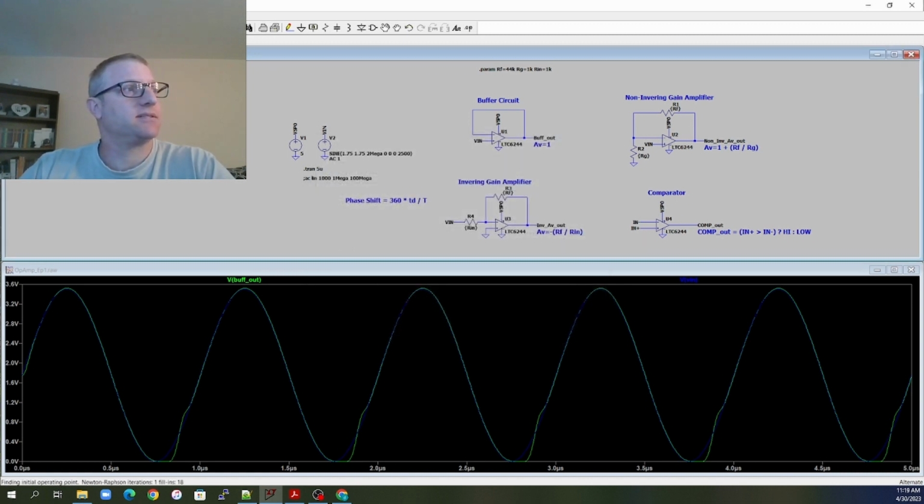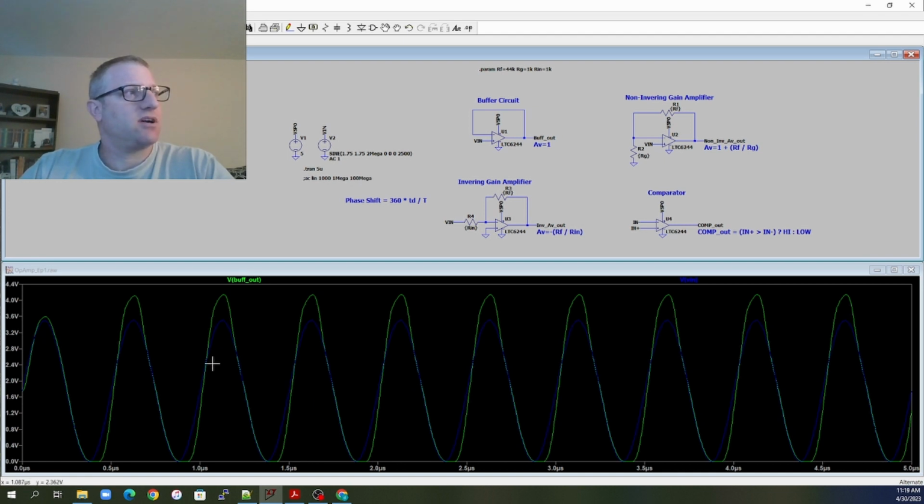and we run 2 megahertz, you can see we start beginning to get some distortion, right? We haven't violated the input, but you can kind of see that our output is going higher than our input. So we're getting some slight gain amplification here in the system at this frequency, which could be a byproduct because I do not have a gain on this. It should just be input to output. So there might be something internally on this op amp, which is causing this anomaly of having this gain